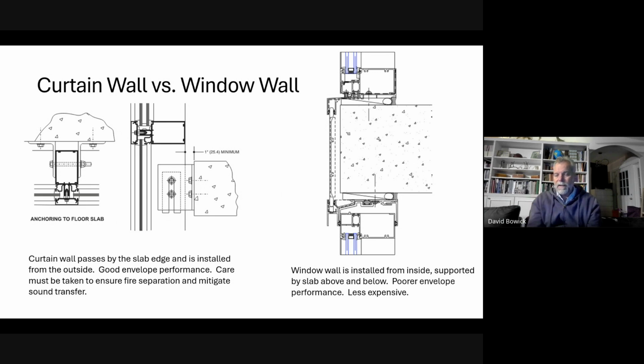Dotted in here is a window wall spandrel panel. So a separate piece that's installed from the outside to cap and insulate the edge of the slab. So it's not a radiator condition like that image I showed before, where the slab edges are exposed to view and simply radiating heat to the outside. The slab edges are covered with a nominally insulated cover.